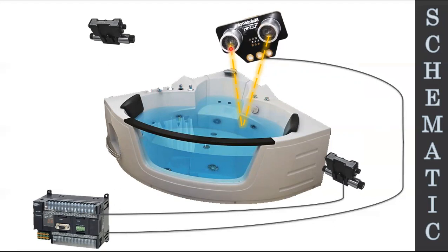Now, the orange color here is a signal of sound, no? Ultrasonic, ultrasound, ultrasonic, no? So it emits sound. When it strikes the water, it bounces back. So the sensor could determine the distance, no? It converts into electrical signal and feed it to the PLC, okay? And then the PLC will provide electrical signal to your valve so that the valve will open or will close depending on the level of the water.